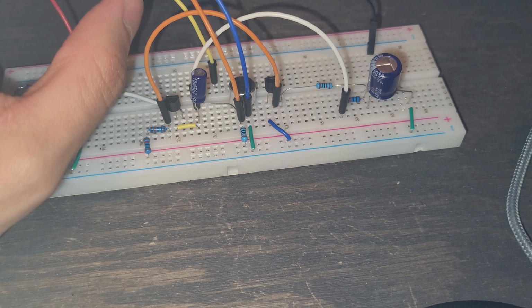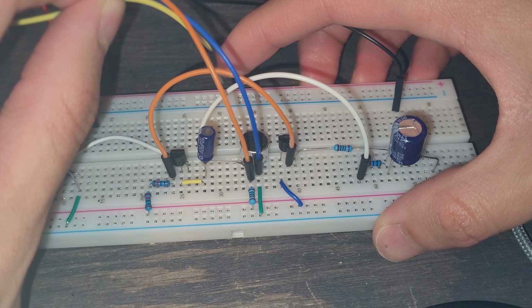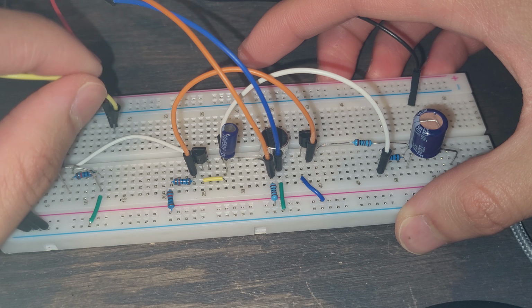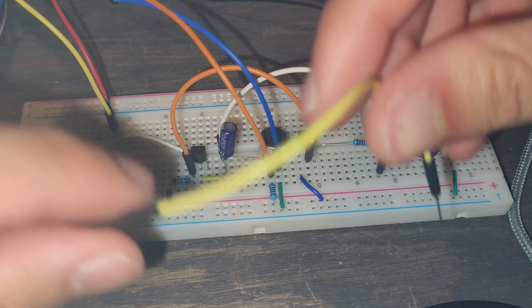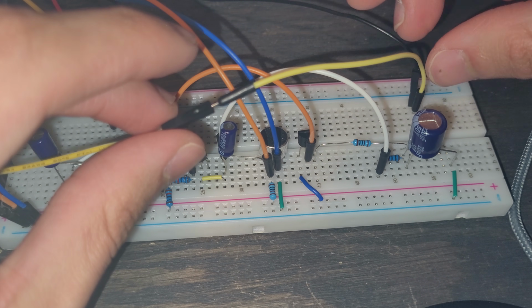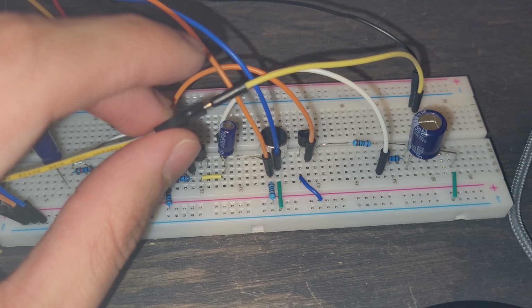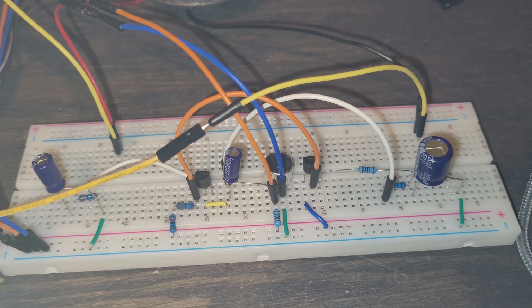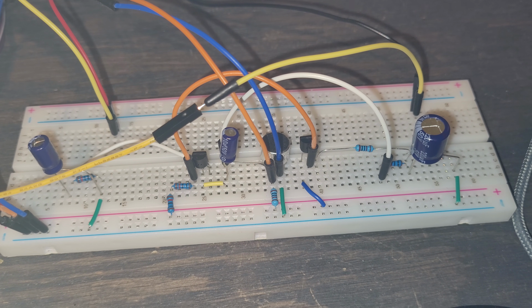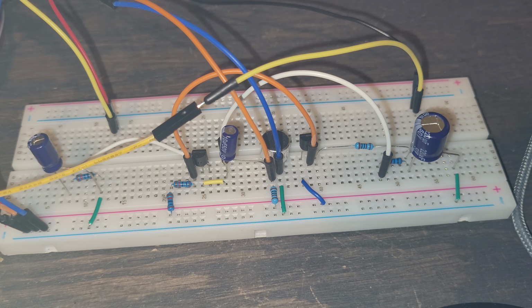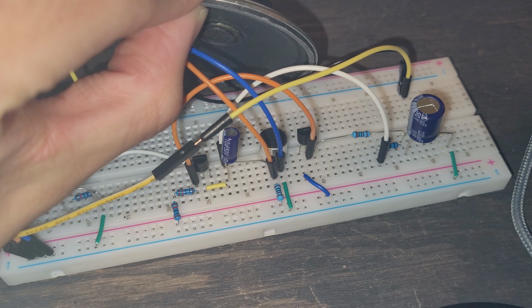What we're going to want to do is we're going to take this yellow wire, the one without the white stripe, and we're going to put it with our speaker, and then we're going to take the other waveform wire that has the yellow and the white stripe, and we're going to plug it in. And if we look at our waveform generator, we should have a 1 kilohertz frequency, so it's going to look like this, a 1 millisecond period, a 2 volt amplitude, 0 volts offset. Now if we want the sound to be higher, we can change the amplitude. It's 2 volts now. I'll make it 2.5, press enter and run all, and it's louder. That's coming from our speaker right here.